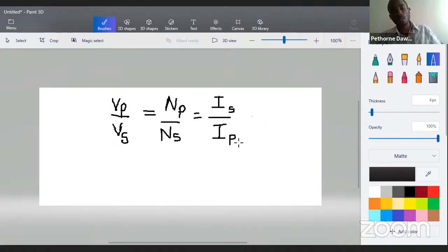All right. The reason for that is because of the equation for electrical power. V times I is actually a constant. And when you transpose our ratios, this is what you'd end up with. So just bear in mind, important, that current and voltage in terms of a transformer are inverse, so to speak, when it comes down to writing the ratio.